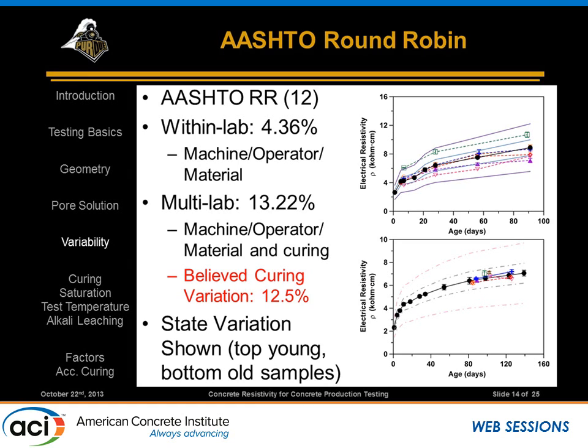Now, if we asked anybody before we started, is handling the samples very important? Is talking about the samples very important? Yes, it's vital, but these are all following the standard. All right, so everyone was following the AASHTO provisional standard here, curing the samples, and the variation was very, very high in the system.